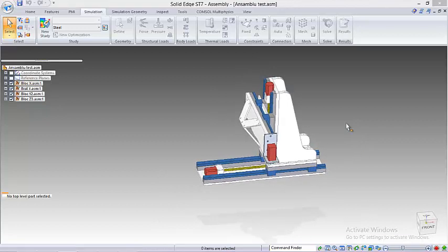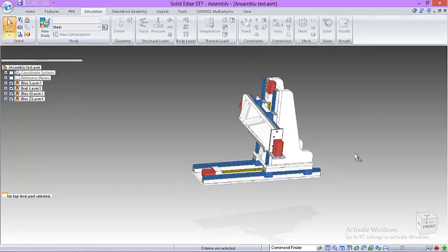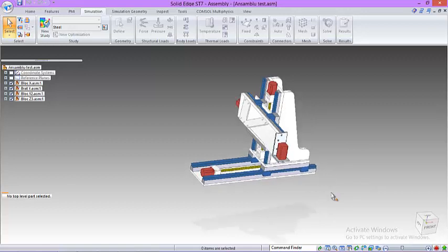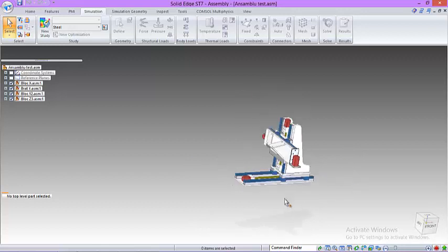Okay, so the total power of the equipment is going to be 1 kilowatt. This is only half of it. So that 1 kilowatt is going to be divided between 6 stepper engines and 2 servo spindles, even though it's going to have 3 servo spindles, but they're not all going to work at the same time. In terms of force, I'm going to look at the linear bearings catalog and see the power transfer per rail to cage, multiplied by 4, and calculate the force that can be transferred between the moving elements.